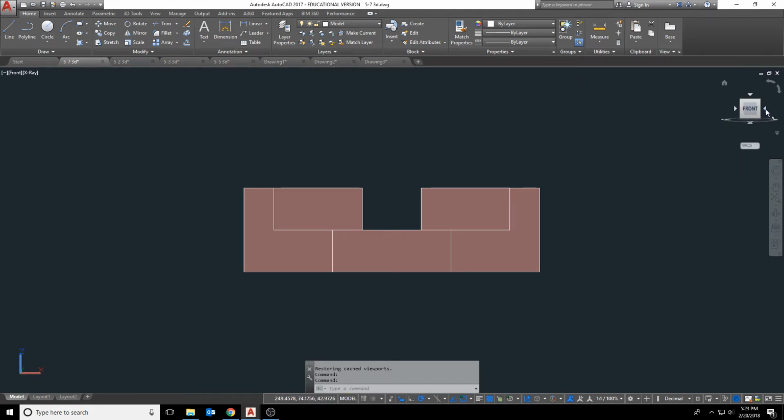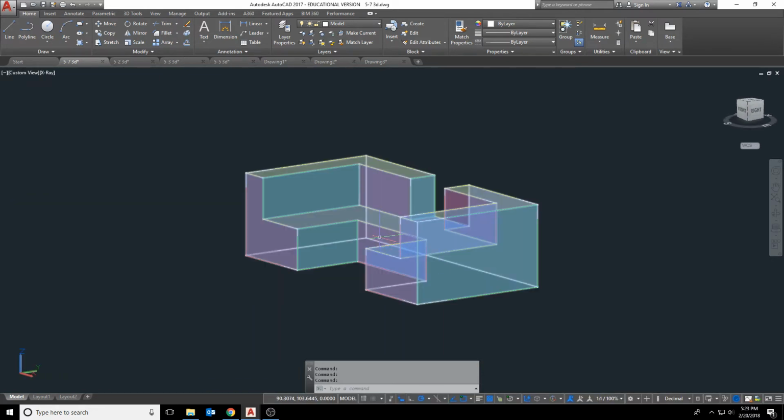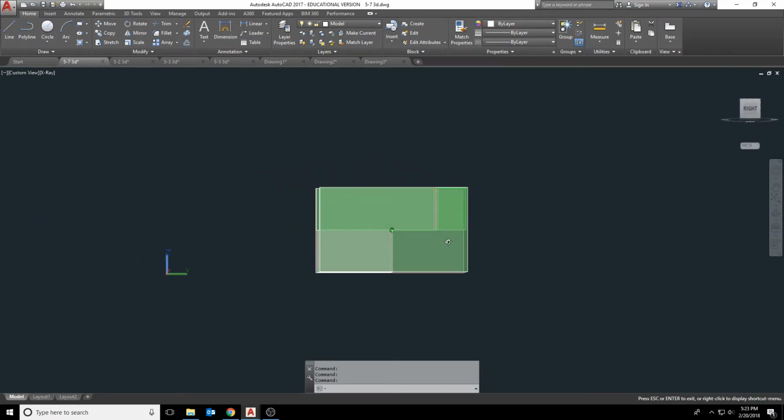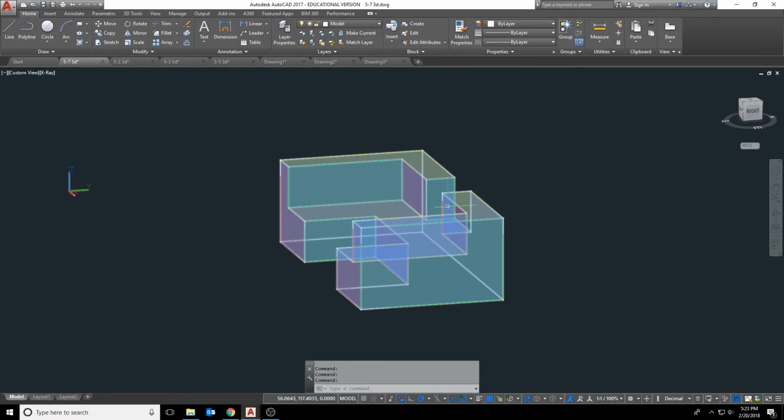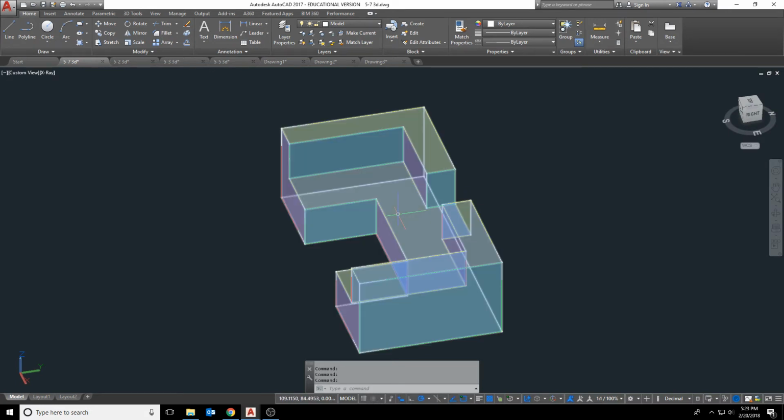The view that gets a little bit complicated is the right side view, because the only visible line in the right side view is the outside rectangle. All the other lines on here are hidden. So if we take a look at where these hidden lines come from, this hidden line right here is this back face right here. The hidden line that we see over here comes from these 2 back faces, and the hidden line that comes all the way across comes from this face right here.